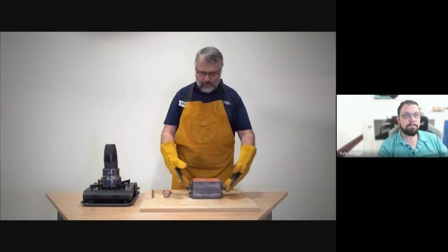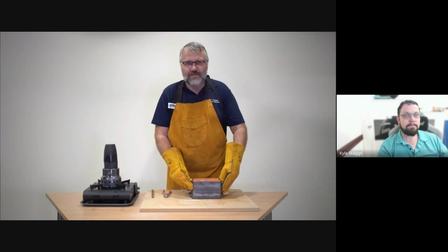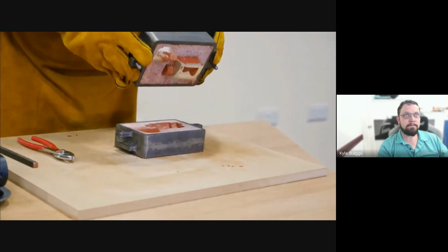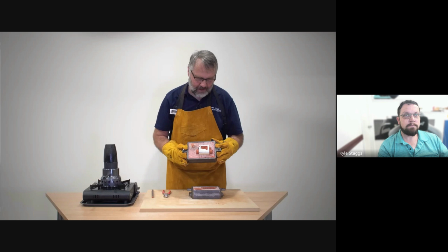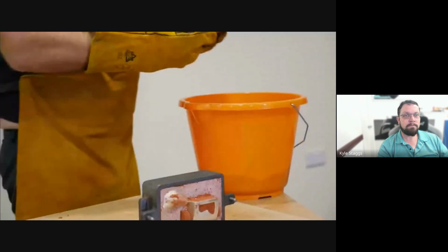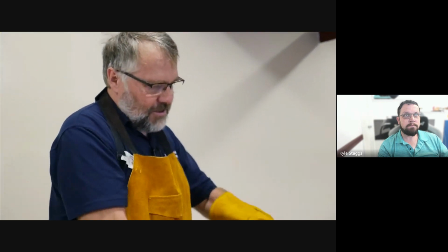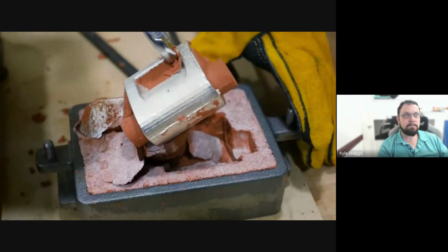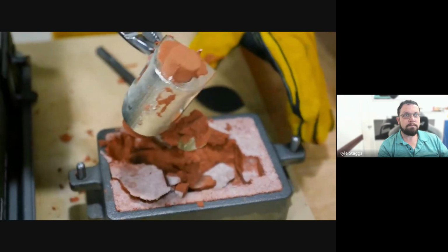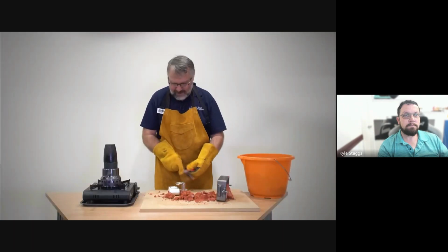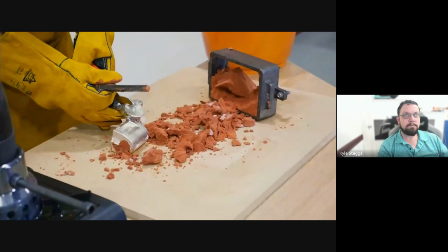Okay, so we've let the mould cool down for 10 or 15 minutes. So hopefully, when we open it up, we'll have the magic of a decent casting in there. It's filled well on the bottom part of the mould. Because we've only used a low temperature metal, the sand hasn't really been compromised. We can now break out the casting. It is still hot. You still have to be remembering that it will hurt you if you pick it up.